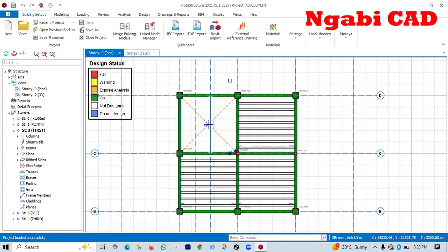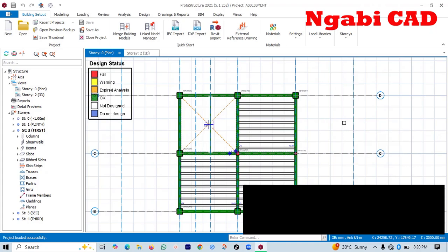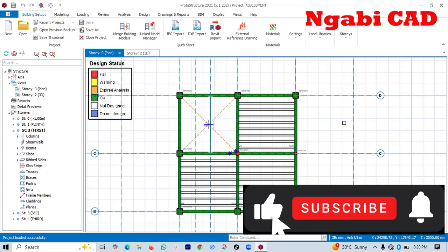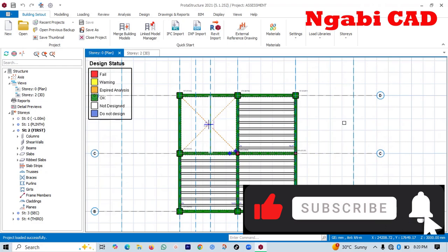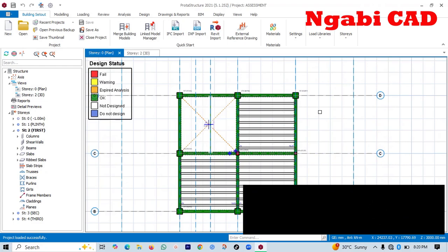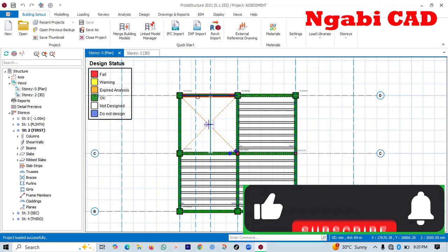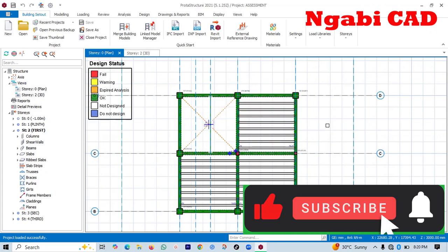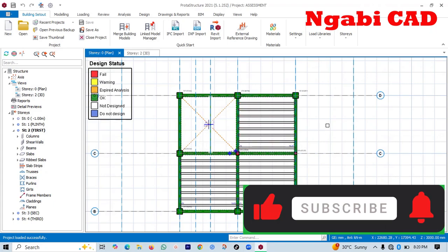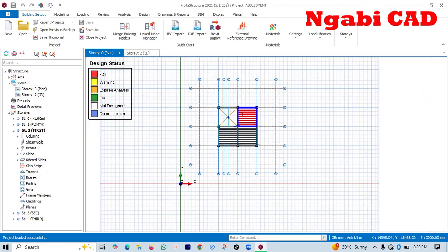As we know, pressure is equal to force over area. As we increase the area of the footing, we are reducing the pressure, such that the pressure equals the ultimate bearing pressure of the soil, or what we call the safe bearing pressure of the soil. And in this, we can distribute the load safely to the soil.